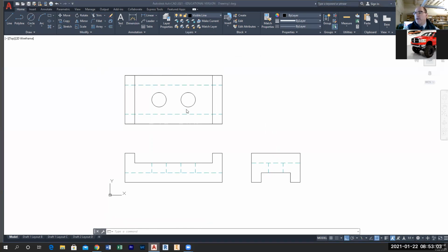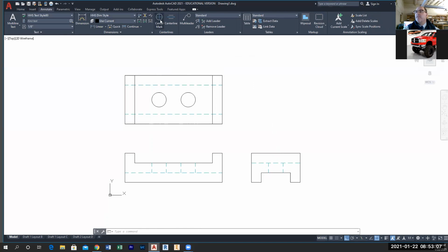All right. What I want to do is put center lines. I go to annotate. This is easy. Annotate, center line. Okay. I'm going to pick this for these hidden ones. Now you notice it doesn't look like a center line, but I'm going to change that in a second. I'm going to show you how to do that too. Okay. There's a center line. And then pick that again, and I'm going to put a center line here and a center line here.